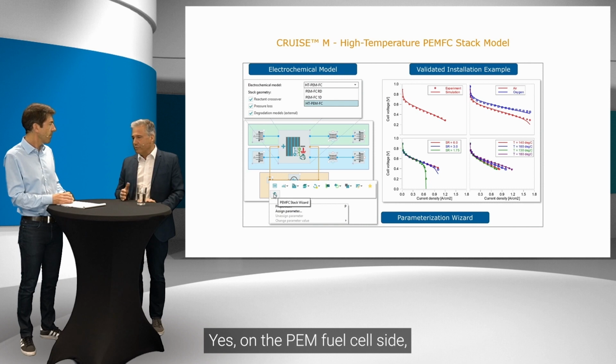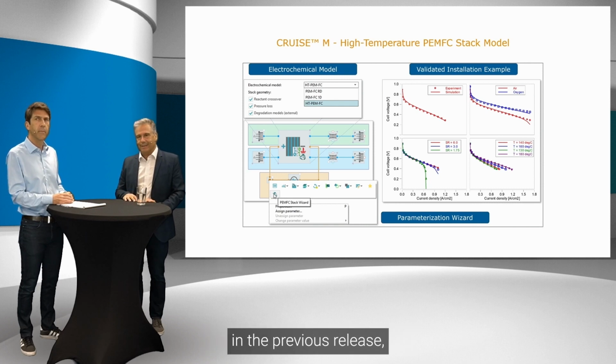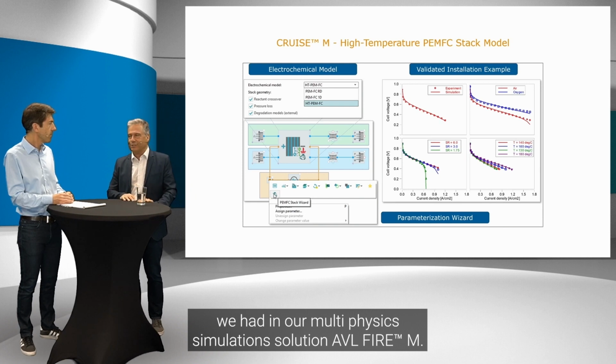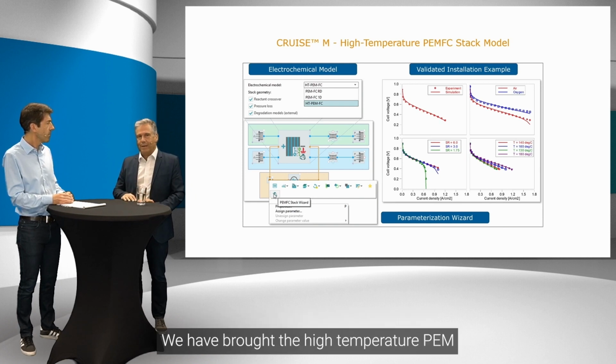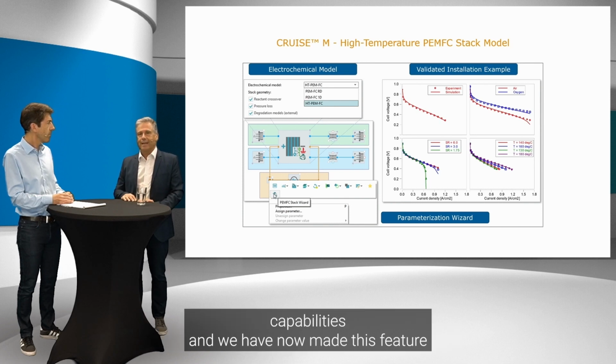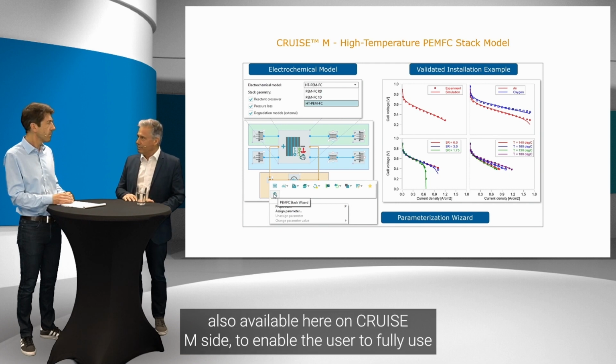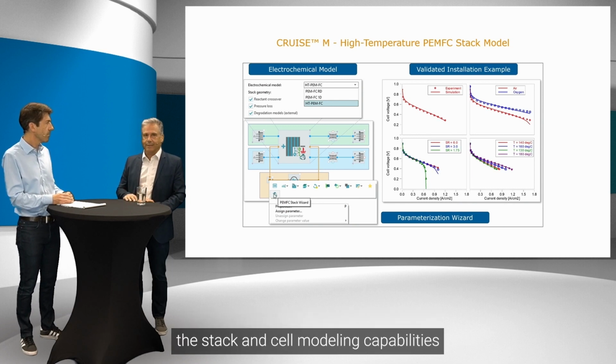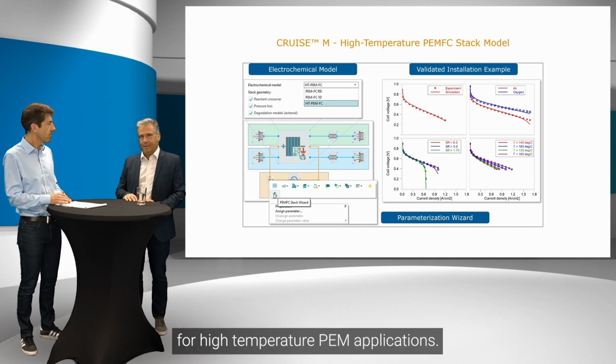Yes, on the PEM fuel cell side, in the previous release, we had in our multiphysics simulation solution FIRE-M, we have brought the high temperature PEM capabilities, and we have now made this feature also available here on the CRUISE M side, to enable the user to fully use the stack and cell modeling capabilities for high temperature PEM applications.